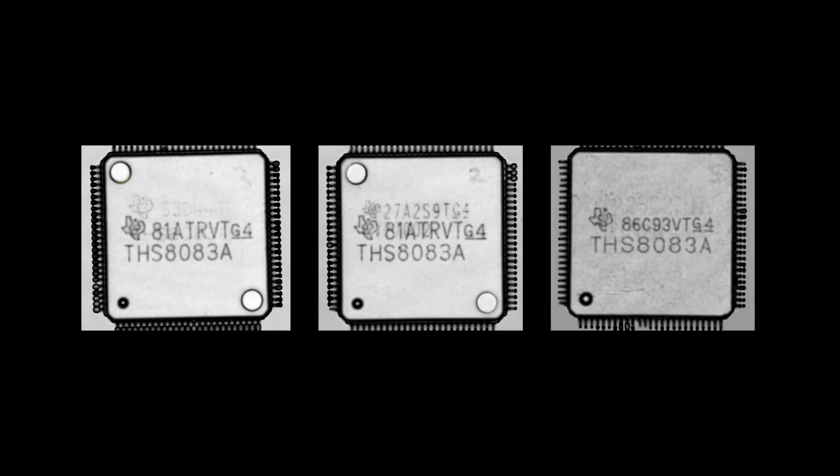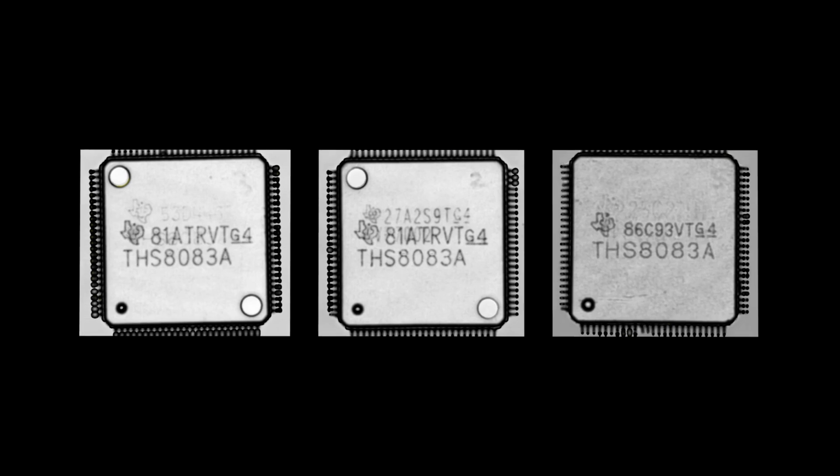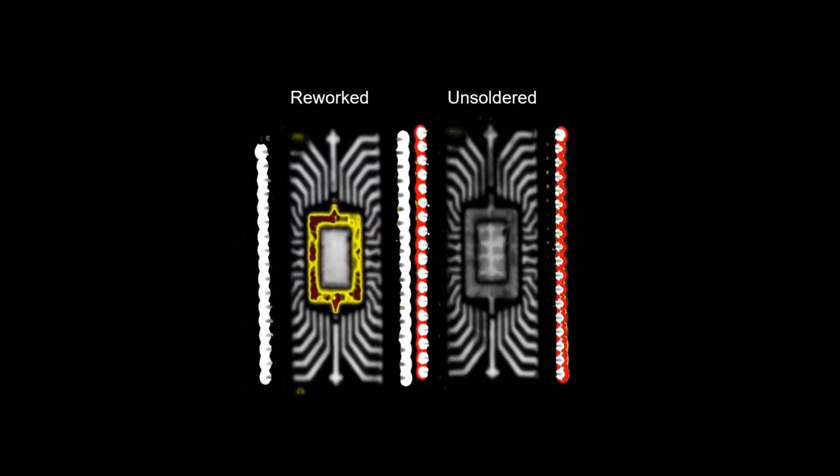This is a reflected mode scan of the package surface. Scanning acoustic microscopy detected ghost markings in these black-topped counterfeit parts. The part on the left was soldered by hand. An unsoldered part on the right is shown for comparison.